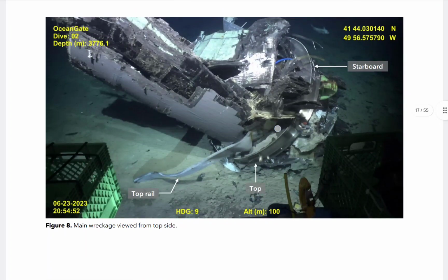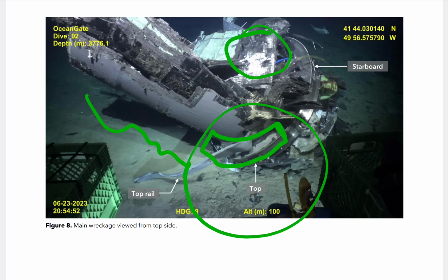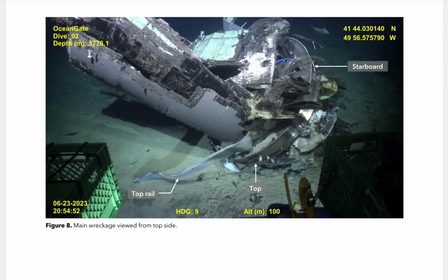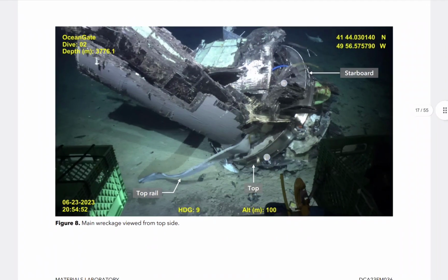And here is the epoxy. We can see it slid, we pushed it off. So again, I think the failure is on this side, as opposed to what you're looking at from here. I don't know the orientation, how much of a spin it took. I do believe it took a spin, per the release of the curlicue, I call it, off the ends of this. They did take a rotation during this failure.